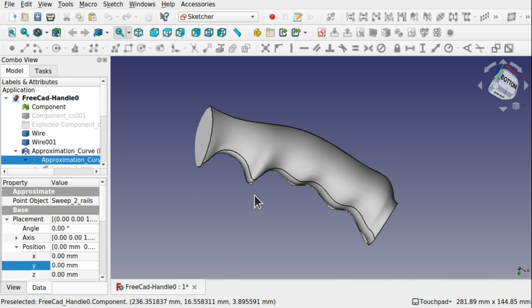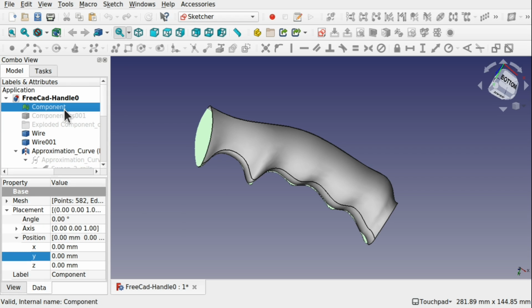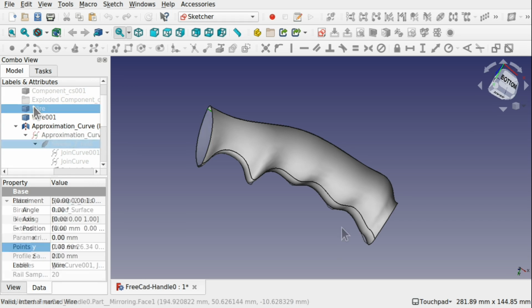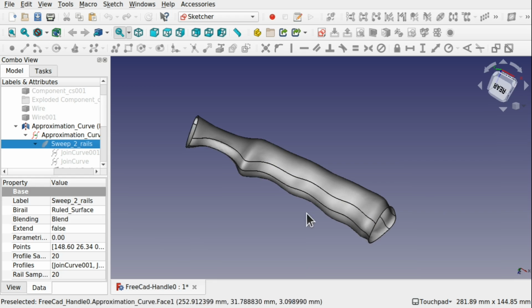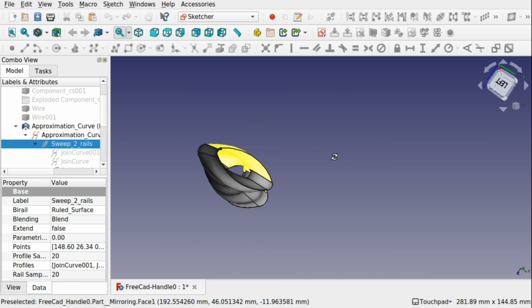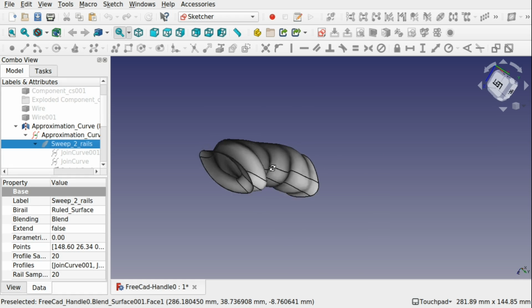What we want to do is we want to make this fully parametric. Now to get this parametric, we needed to take our shell, which was created up the blend curves and the two sweeps, and we had to cap them.